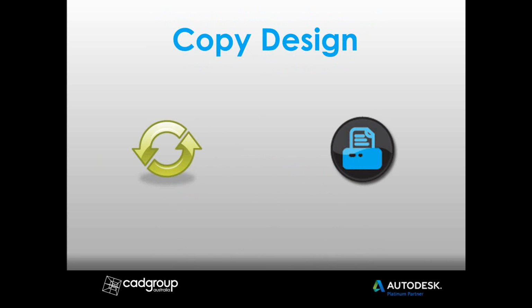So we're now going to talk a little bit about copy design. Now, copy design is one of the most commonly used actions within Vault, no matter what flavor it is, being the basic Vault Workgroup or Vault Professional. Now, I'm going to use Autodesk Inventor here as an example. Copy design will take an entire Inventor assembly structure, including all of the related 2D drawings and 3D models, to derive a new design.